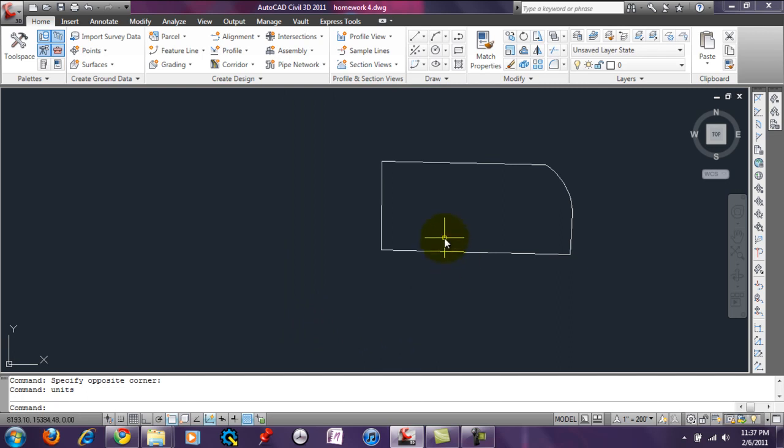Alright, now that we've got the drawing scale set, we need to draw in a fence. And as you noticed on the week that we talked about line types, we had to rescale those line types in order for them to be able to distinguish between the lines. Well, the way we did it before is we just changed each one manually until we could see it, and we just used an arbitrary number.